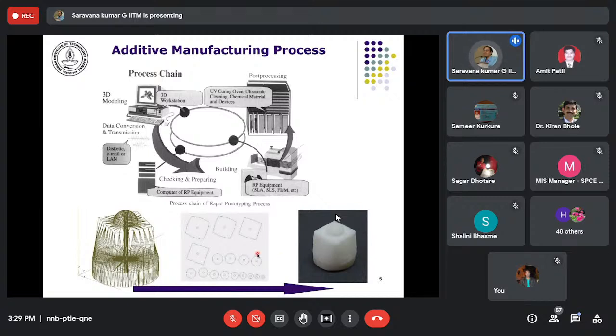And we slice it, and obviously while slicing also there are errors introduced, because you are making a 3D into a 2.5D, and thereby you introduce what we call the staircase effect. I do not know whether people have talked about it. So it introduces surface roughness, unless you keep the layer thickness, the number of slices that you are making, small. If you keep them too small, like let's say 40 microns or even less, we have this multi-jet printer that I was talking about.